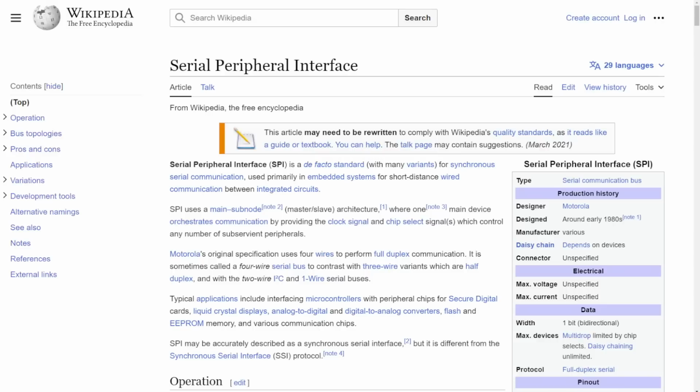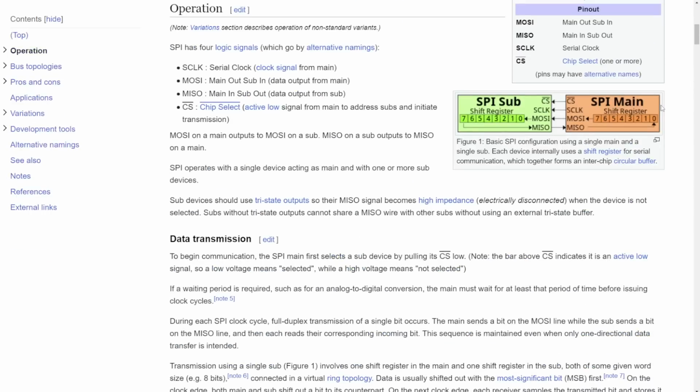So, systems used to communicate between devices in microcircuits, the two most common things I see are I2C and SPI, which is what we're going to look at today. SPI is the simpler protocol, so I think it's a better first look. So on a device, you have 4 lines, the device to the host and from the host to device, and you have a chip select.